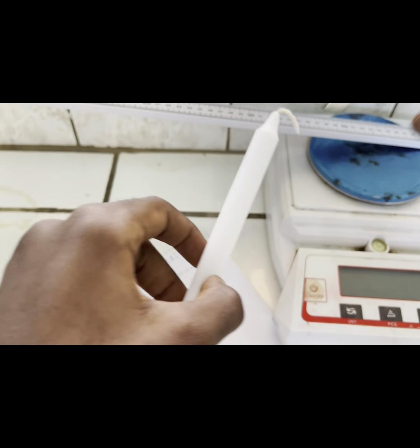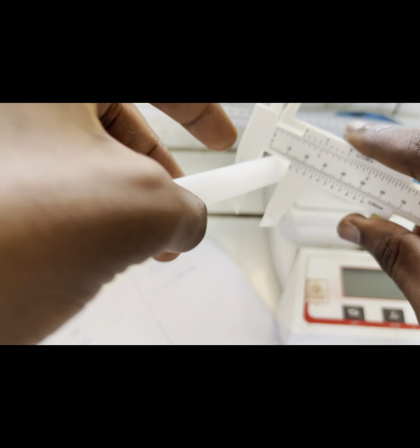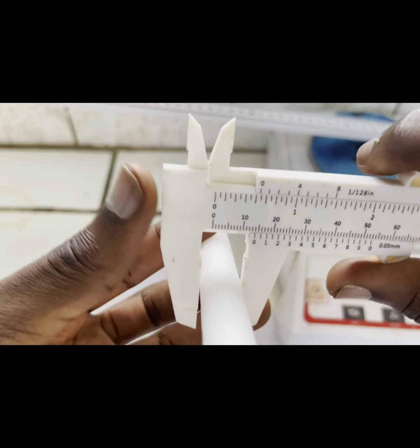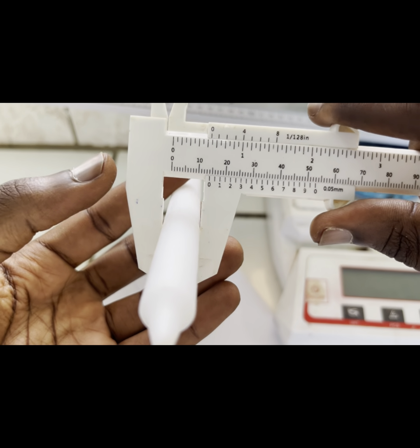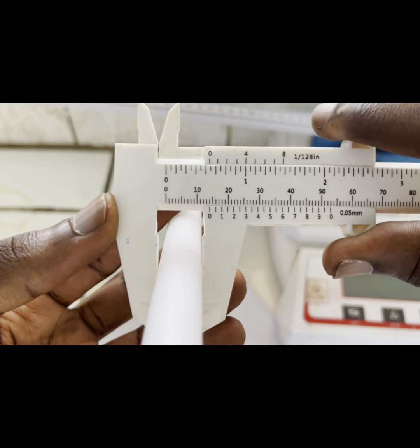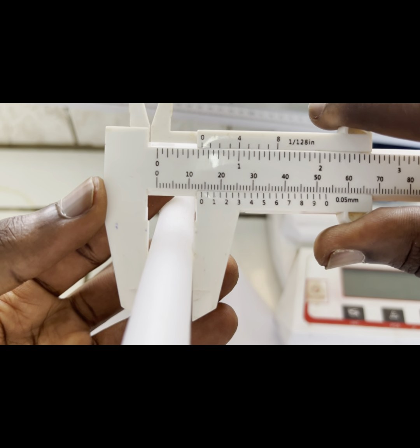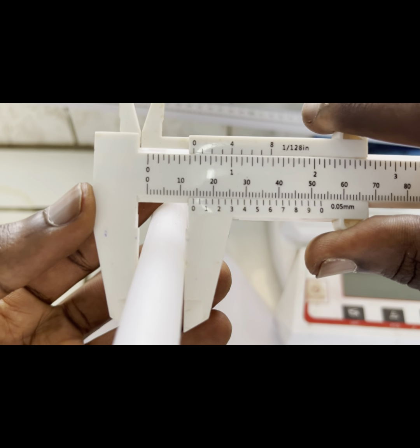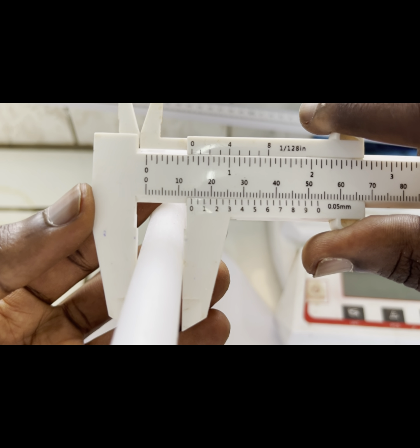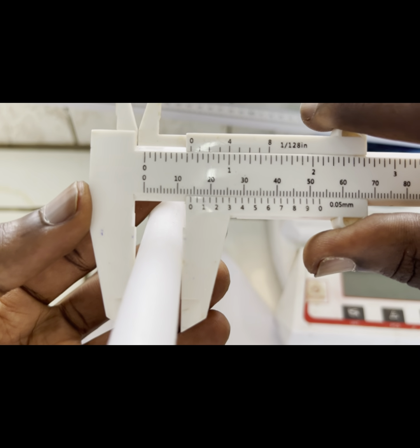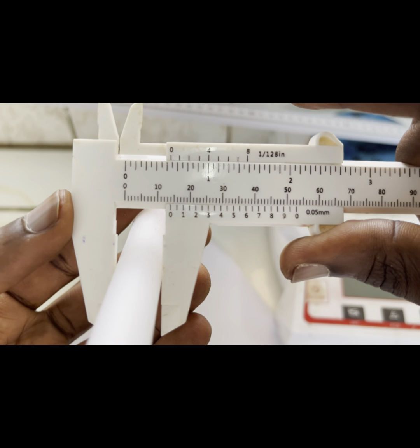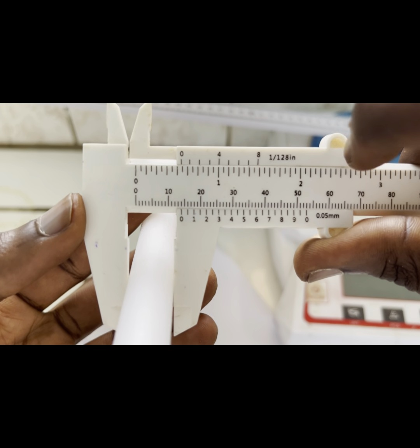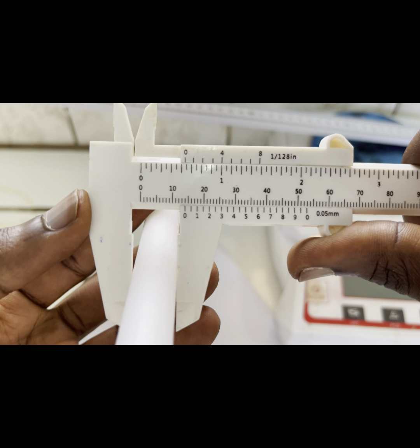Okay, now let us change the position. Let us choose another position to make sure. We don't know if the diameter is constant, if the cross-sectional area of the diameter is the same. So let us find D2. Now here we still have 10, 11, 12, 14. Yes, we still have 14. Then the decimal place now, let us see which number aligns with the one up. I think it should be 8. Yes, 8 aligns. So since it's only 8, I'll put 14.80.